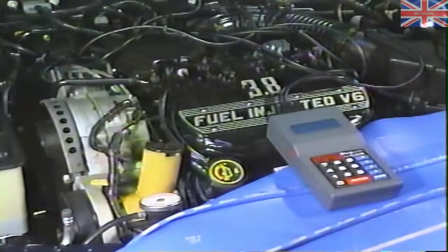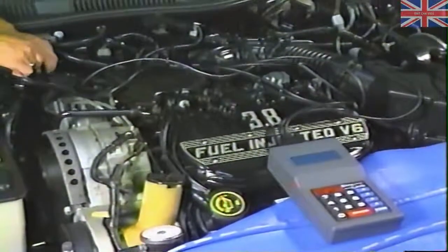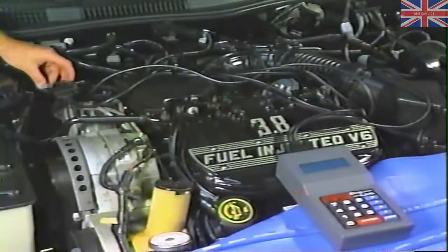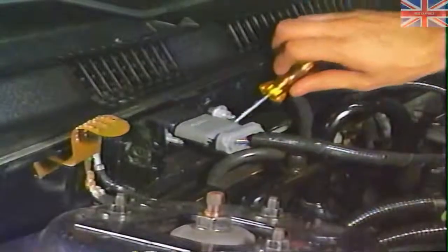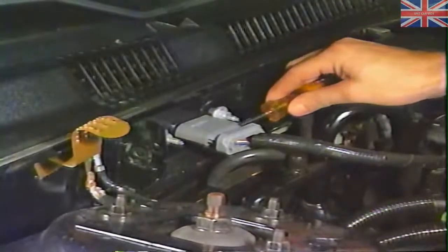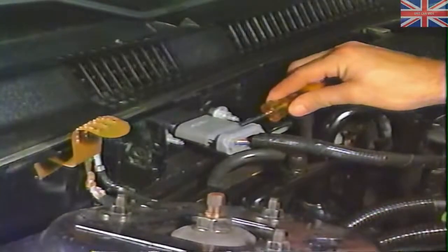We have checked timing advance and it functioned during the test period, but the fact that we have a continuous memory code 18 indicates that at some time in the past the system might have reverted to base timing. This could be the cause of the intermittent problem. With the system in continuous self-test and the engine running, move the wires from the TFI assembly. A code 18. Shut off the engine and disconnect the TFI module lead wire harness and inspect the connections.